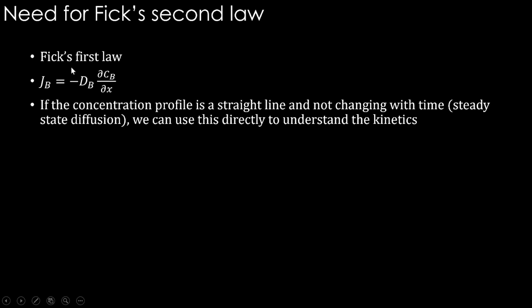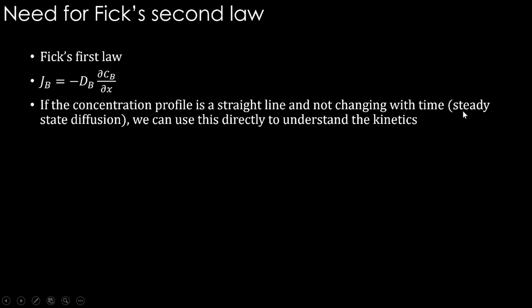Need for Fick's second law. Fick's first law is this, but it can be used if the concentration profile is a straight line and does not change with time. If the concentration profile is a straight line, meaning dc by dx is one value for all the locations, all the different x values, dc by dx is constant, then it is easy to apply Fick's first law and get the flux, diffusivity and things like that.